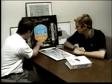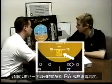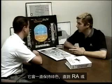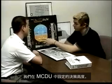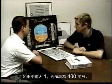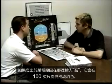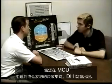Describe to me when you would get your RA, or radio altitude. The radio altimeter comes into play below 2,500 feet AGL. It'll be green all the way down to 100 feet above whatever RA or decision height we have set in the MCDU. It defaults to 400 feet if you don't enter one, and if you enter no DH in there for whatever reason, it would turn amber at 100 feet. DH will appear anytime you're at or below your decision height set in the MCDU.